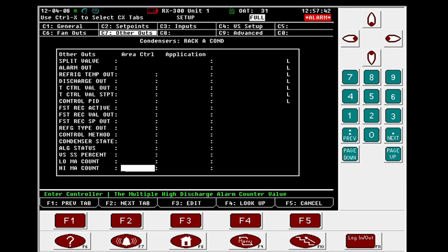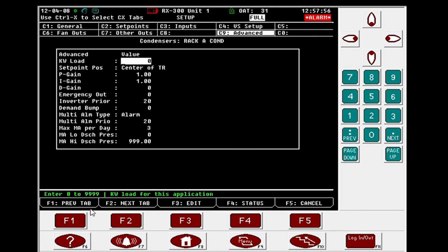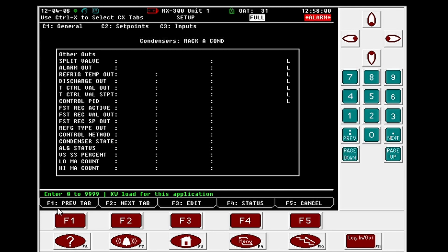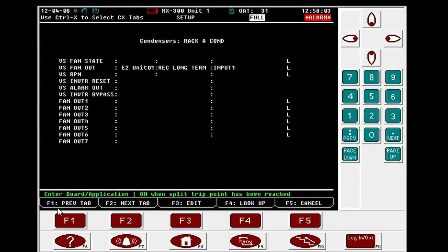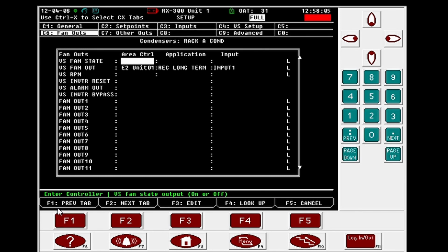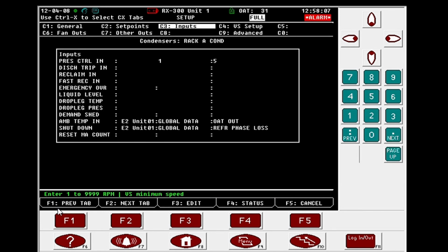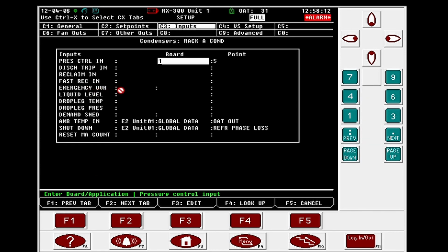Wow. So basically, you could network it from the condenser, the refrigerant temp, or refrigerant level, out from the condenser. Yeah, the liquid level. You could tie that liquid level input to that new one we made.